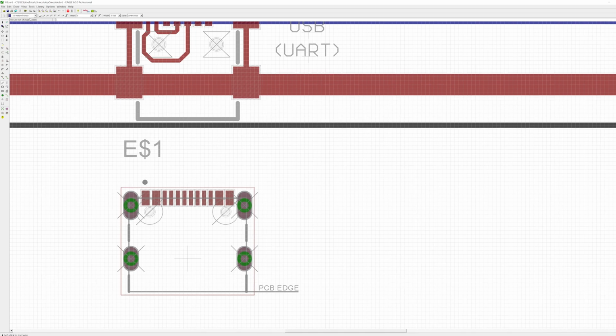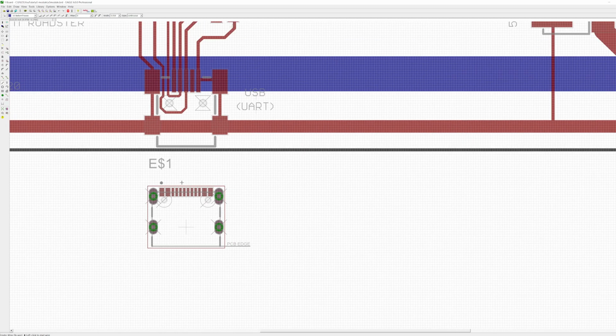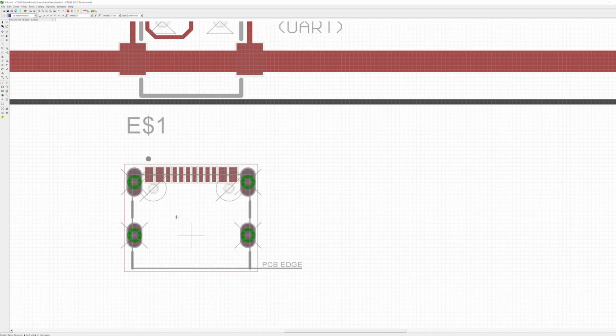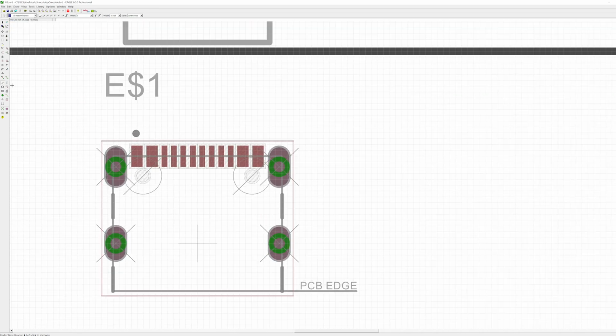So real quick, I'm just going to draw a blue line from the dead center of the other connector. Okay. And we can see that it does go right through the dead center of that little cross indicator there. So we do know that this is dead center on our board. And that just makes it easier when we're changing grid sizes, that it'll probably be more compatible.